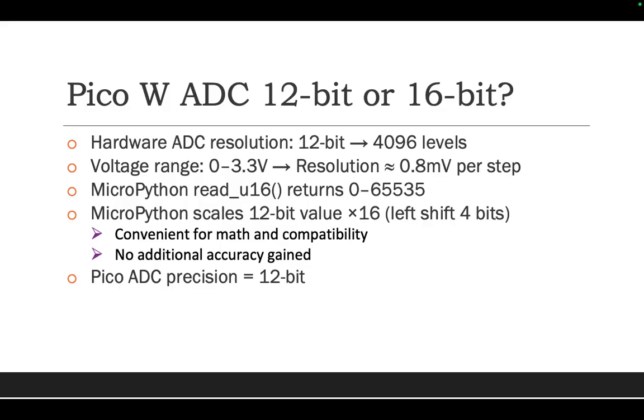The 16-bit is just when MicroPython reads the voltage, it doesn't expand the resolution. The resolution is always about 0.8 millivolts. It's 12-bit.